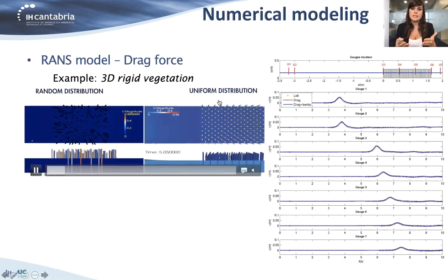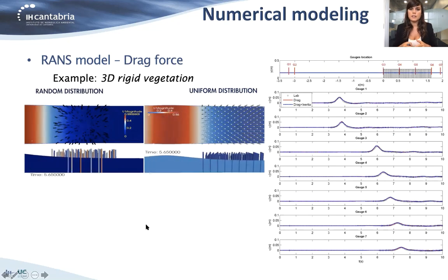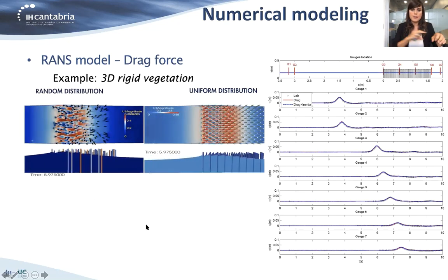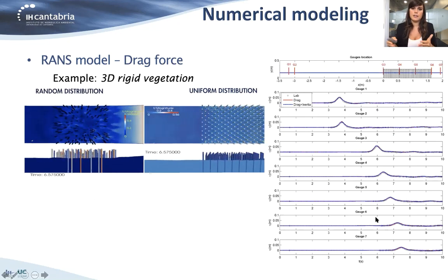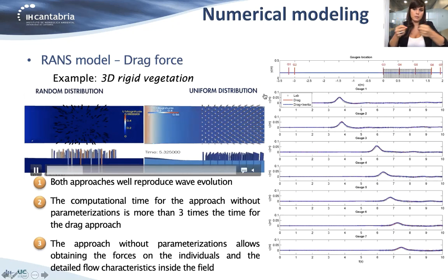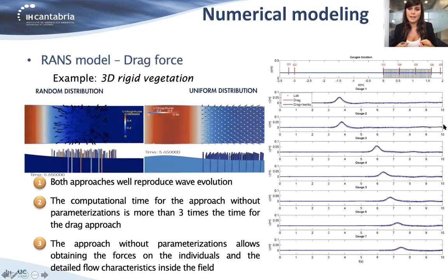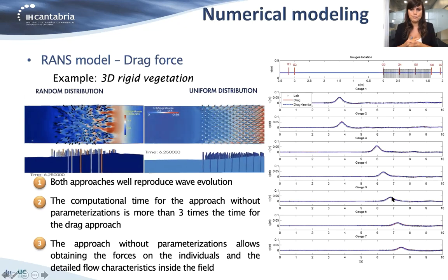Here is an example of two simulations performed, including the individual elements. And also in the figure, you can see the good assessment of the wave decay obtained with the model, including the drag force. In both cases, the wave decay was well represented, but the computational time for the approach including all the individual elements was more than 3 times the time needed to run the drag approach.